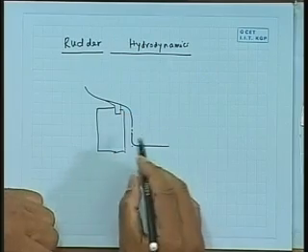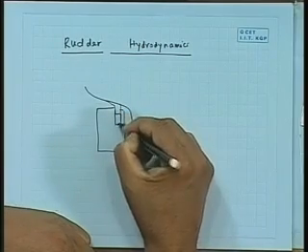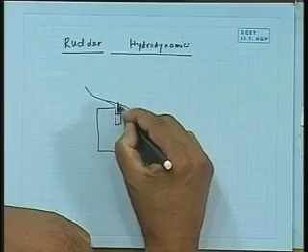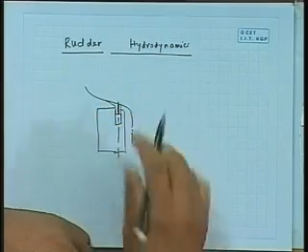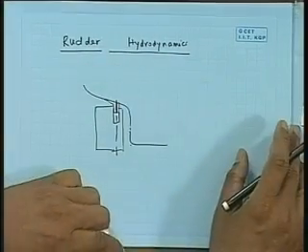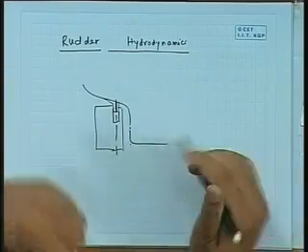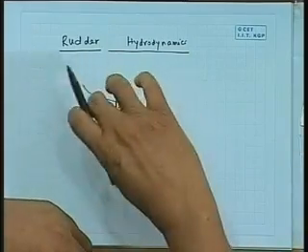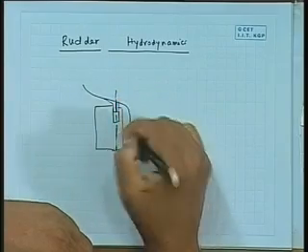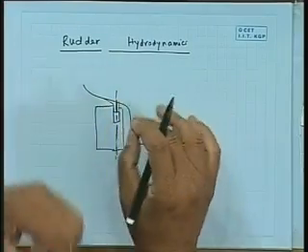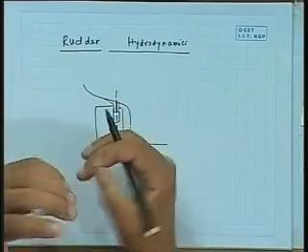There are rudders which are balanced, not balanced, having a post. Number of types of rudders are there. Essentially rudder is a device which you can rotate about some axis, and by rotation it causes primarily force in the y direction. This is what you are interested in. You want to generate turning moment and turning force. This is what exactly it is.